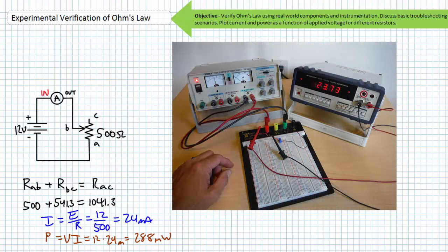Power back on, we're seeing 23.73 milliamperes of current through our resistor, extremely close to our expected value of 24 milliamperes. At least for these operating conditions, Ohm's law is true. Notice we juggled the DMM in ohmmeter, voltmeter, and ammeter mode. And at no time were we ever unaware of our operating conditions, nor did we ever set anything on fire. This is the minimum standard of success.